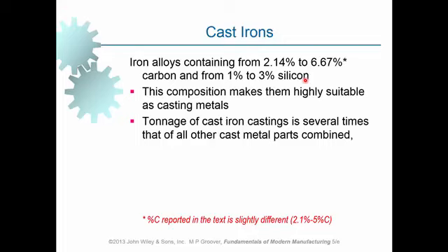Well, what silicon does in cast iron is this. When it is at elevated temperature, it is in the liquid form. We want to cool it down in order to solidify it, in order to make products out of it in a casting process or any other process. If there is not a sufficient amount of silicon in it, a lot of cementite will be formed in the product, and this is not good.